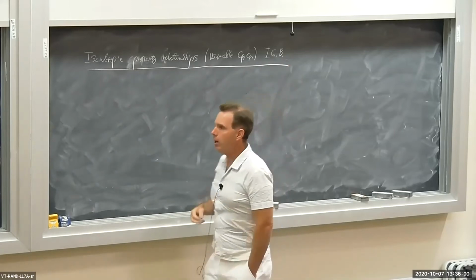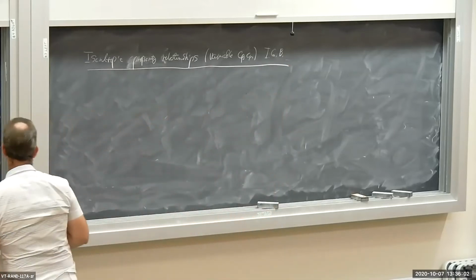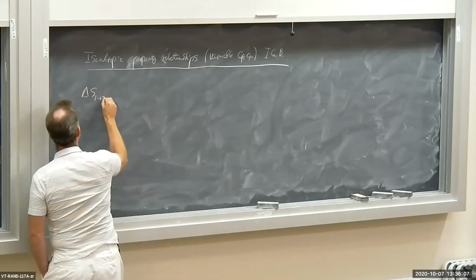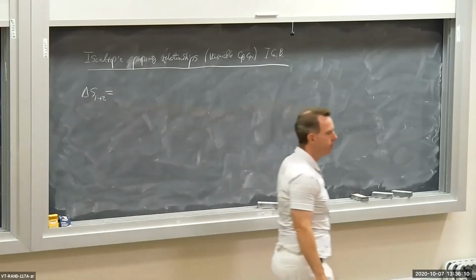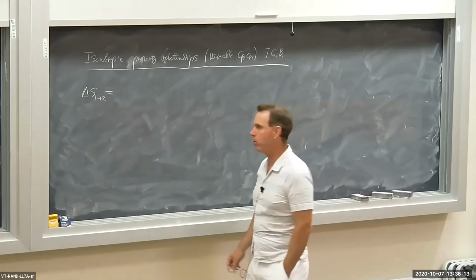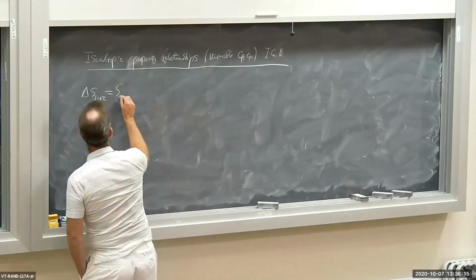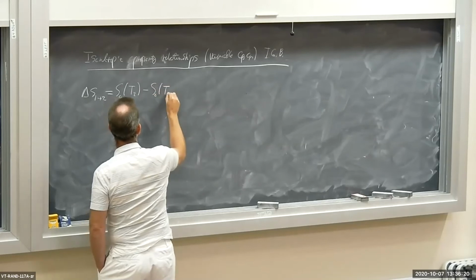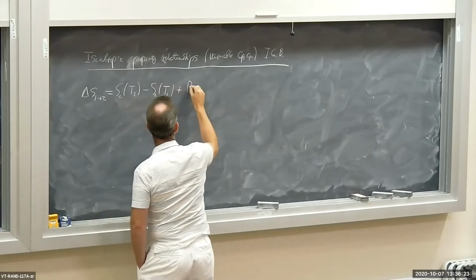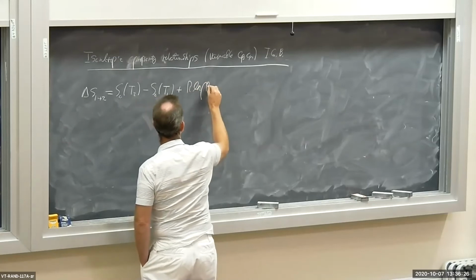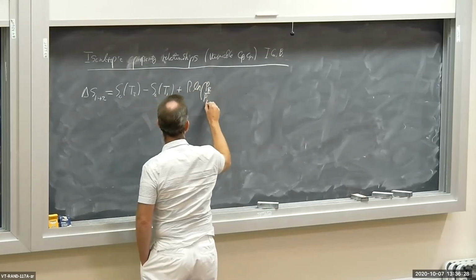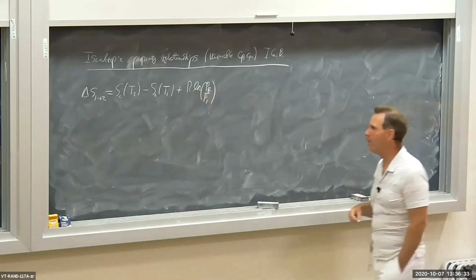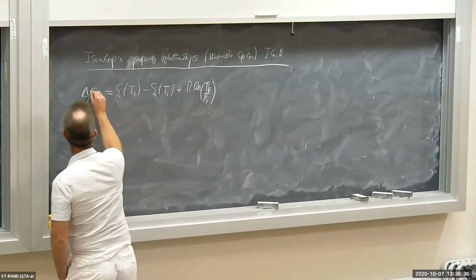Well, let's take a step back here and recall, we had an equation giving delta S for variable specific heats involving those S naught quantities. Remember, it was S naught evaluated at T2 minus S naught evaluated at T1. And then I had a plus R ln P2 over P1. Okay? So if it's isentropic, delta S is equal to 0, all right?